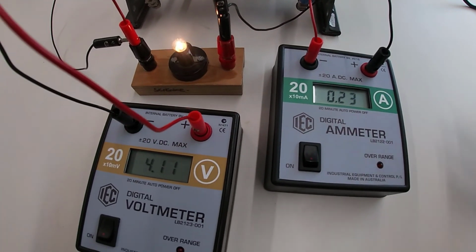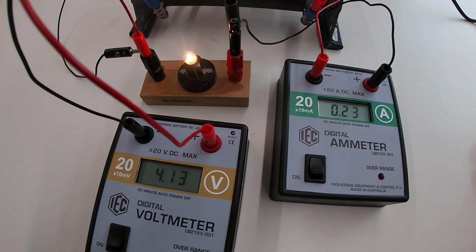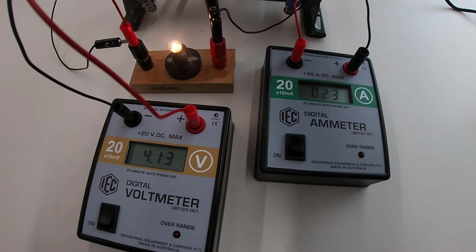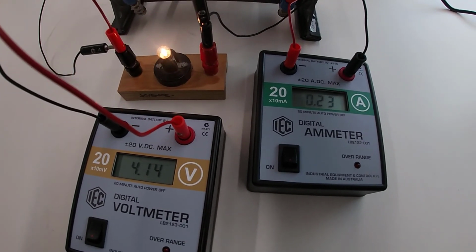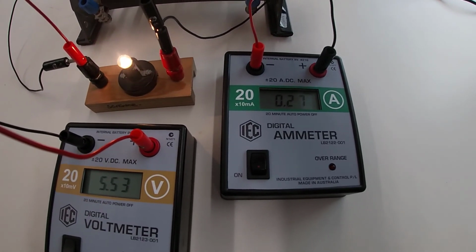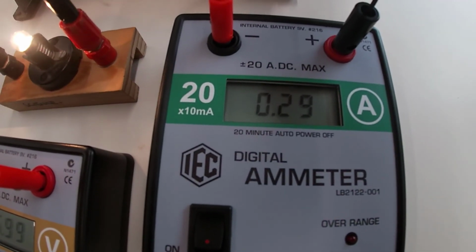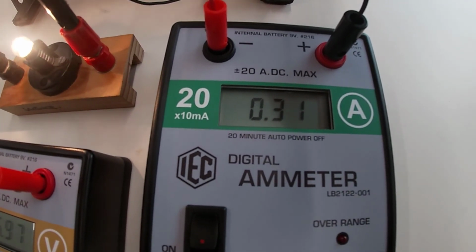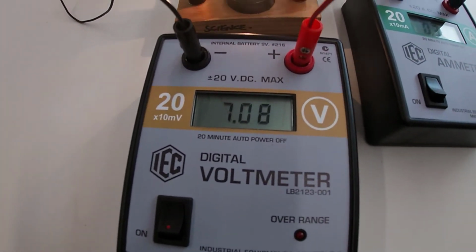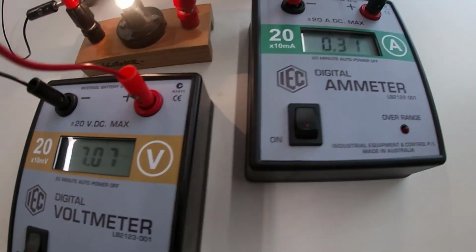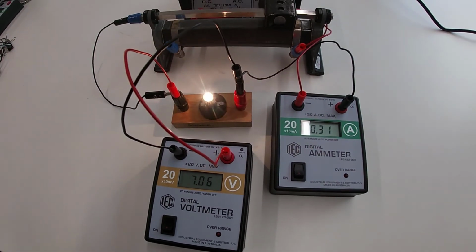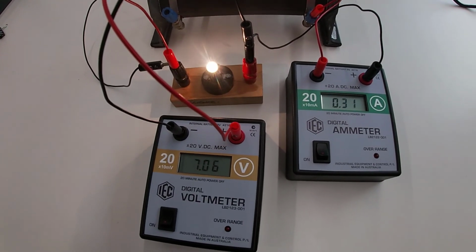So you can see that the amount of current going through the circuit is not proportional to the voltage because I've doubled that voltage and I have not doubled the current. So for me to get the same amount of current as I was expecting, so if I wanted to double the current going through that light bulb, I need to get to 0.32. Okay, and you can see that I need to give it 7 volts. So effectively, I'm more than tripling the voltage just to double the current. So it's no longer that linear relationship that Ohm's law gives us. So that's a demonstration of Ohm's law.